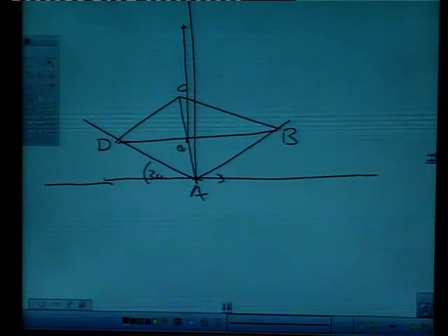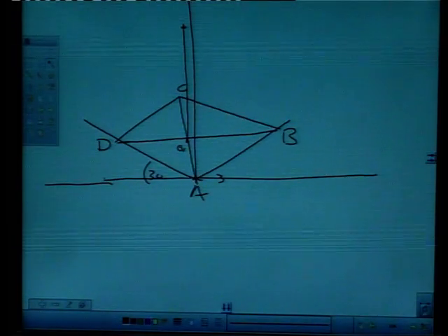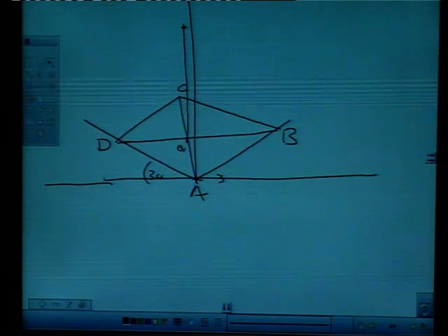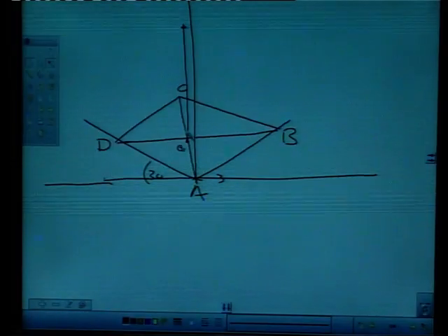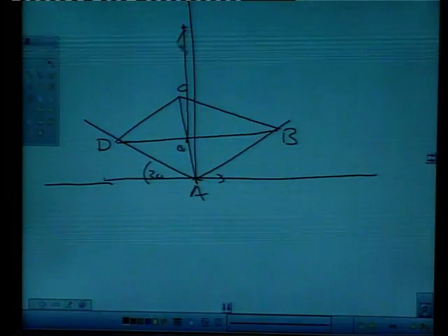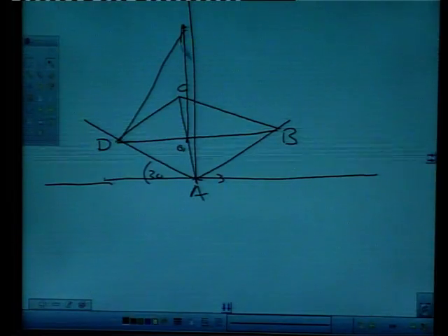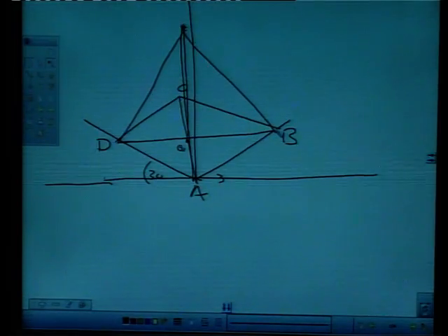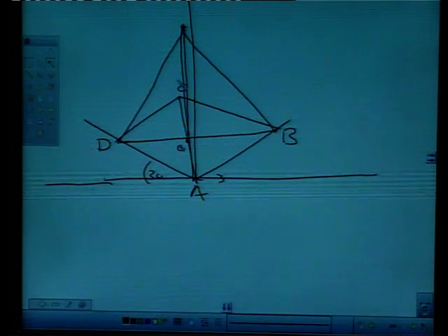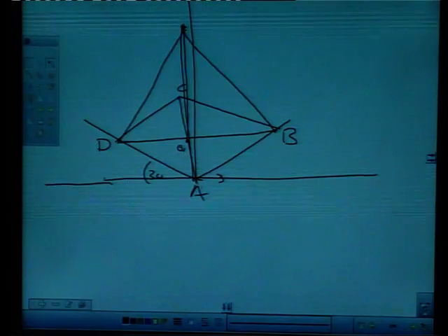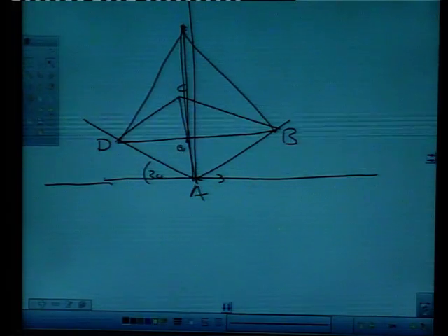First, we will work out the base of the axis. Base of the axis will lie in the center of the square pyramid's base. So, here we have marked 10 centimeter. This is 10 centimeter from here to here. Now, join all the points like we can join point C also. That point will be hidden basically. So, this will give us isometric projections of a square pyramid, right?